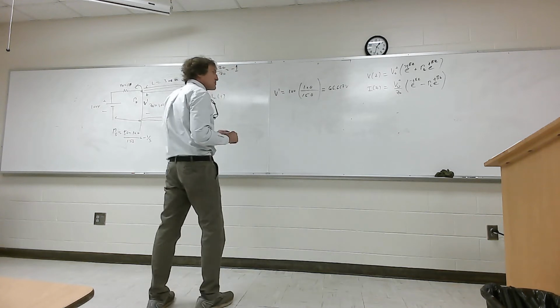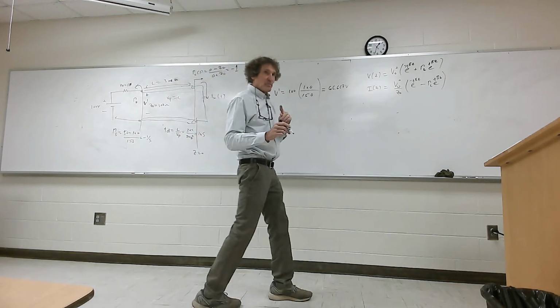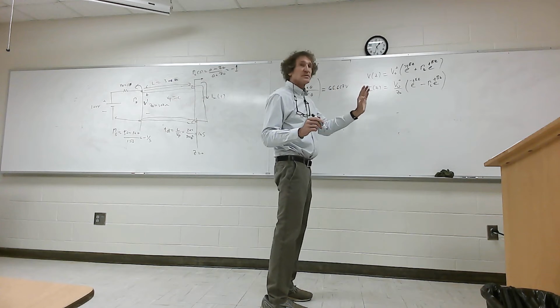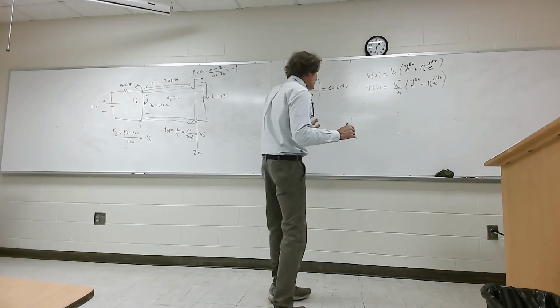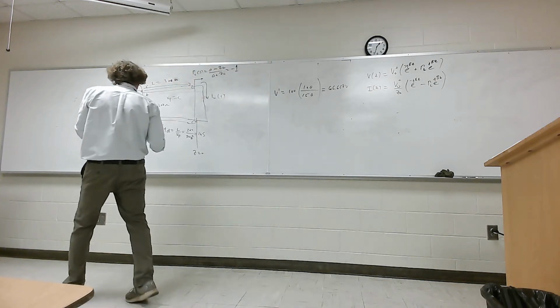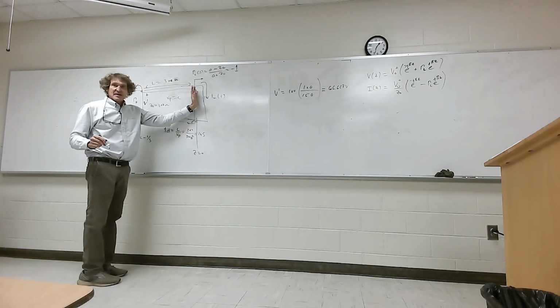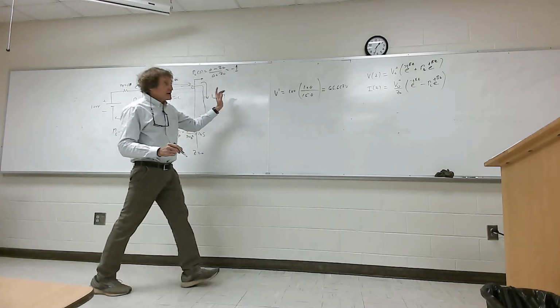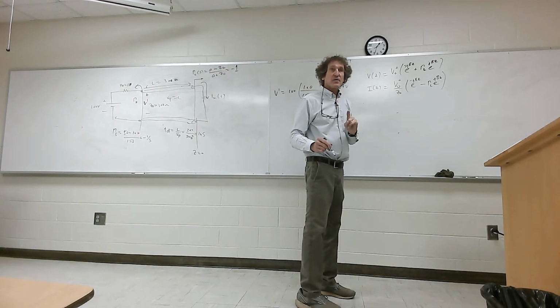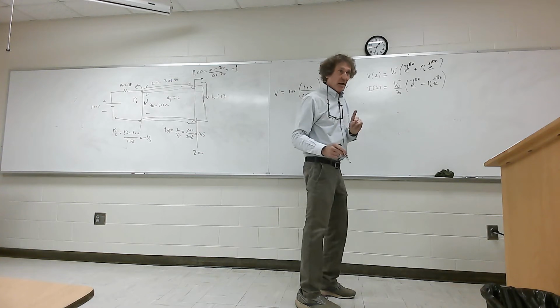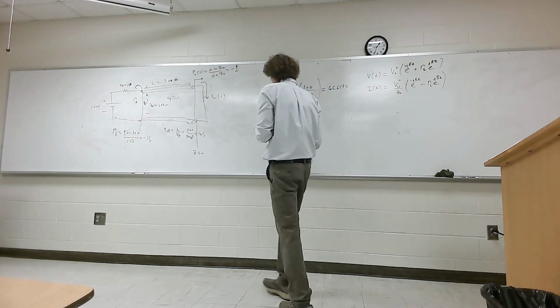So now we come down here, and if you look at this, I could do the voltage waveform, but I'm just going to say one thing before I do. Nothing happens until the waveform reaches there after 1 microsecond, right? But after 1 microsecond, what happens? This V prime impacts it, so it's going to be V prime divided by Z naught times 2 that will give me the value of the current. You all follow me?